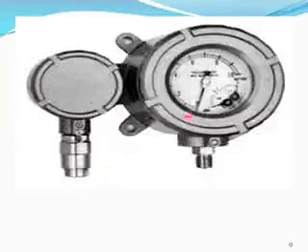This is electrical. This is the most used in the process industry. This electrical gauge is showing the pressure. We apply the pressure here and measure the semiconductor conductivity, according to some transistor inside, and it shows the pressure here. And these wires transmit this value into another system, for example a PLC.